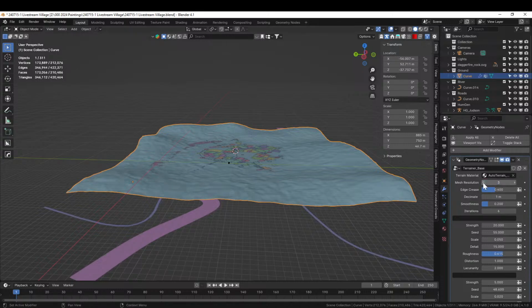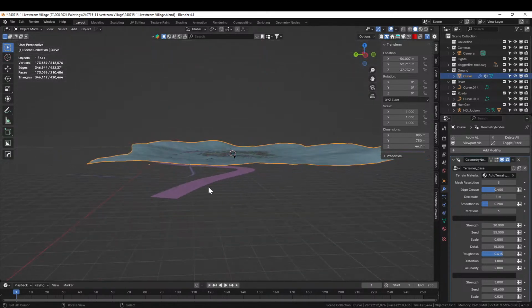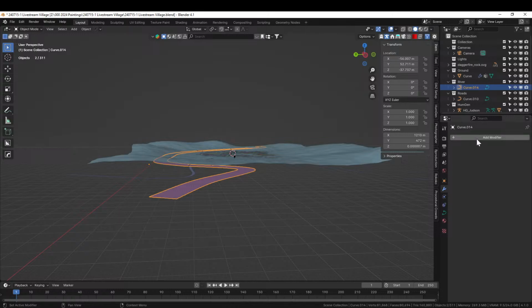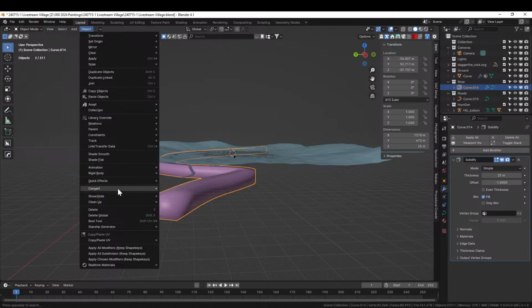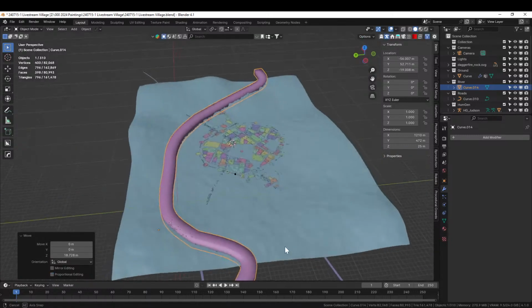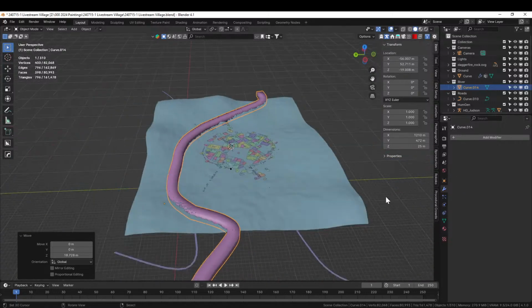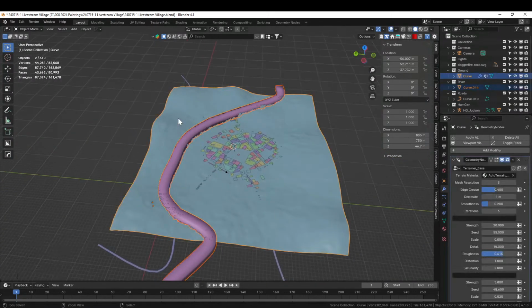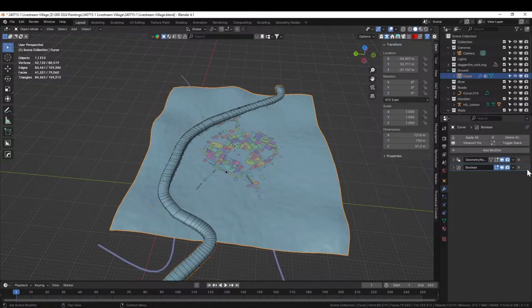Let me take my red filters down to 3 too. Decrease our number of faces. Now this sucker, let's do this. Add modifier, solidify, we said 25. Good. And this one, object convert to mesh. Bring it up like that. That feels good to me. And that, and this, control minus. The boolean needs to be before.